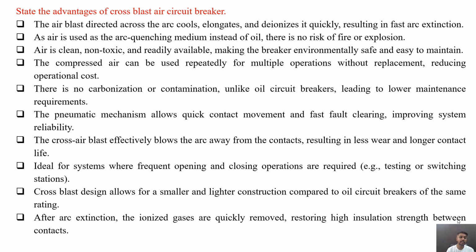Cross blast design allows for a smaller and lighter construction compared to oil circuit breakers of the same rating. After the arc extinction, the ionized gases are quickly removed, restoring the high insulation strength between the contacts. So these are several advantages of cross blast air circuit breakers.